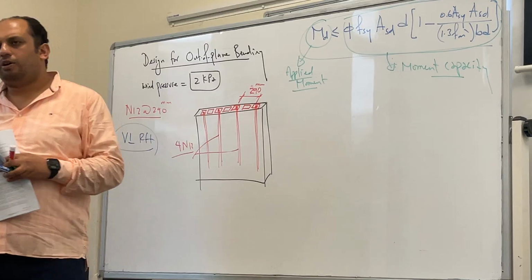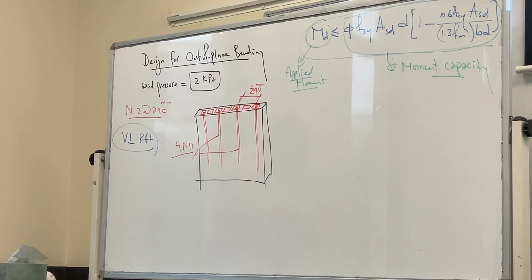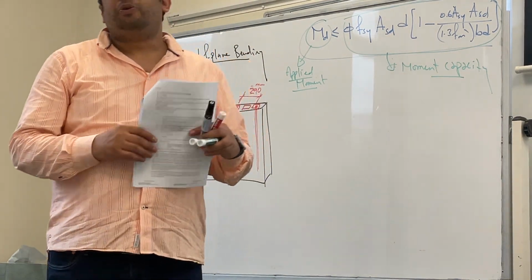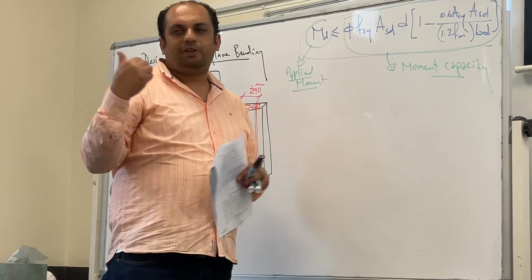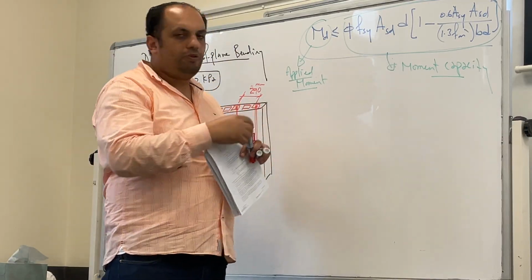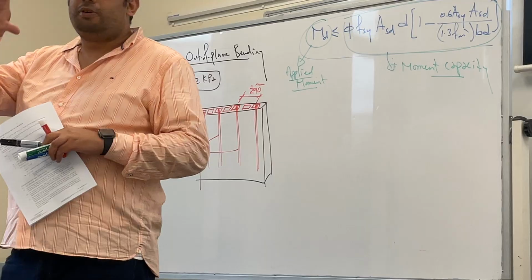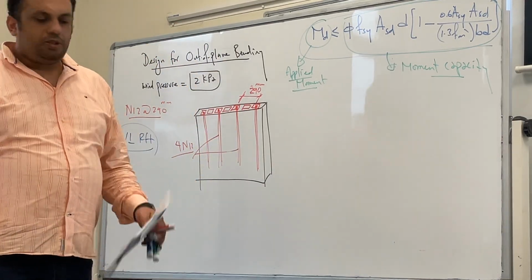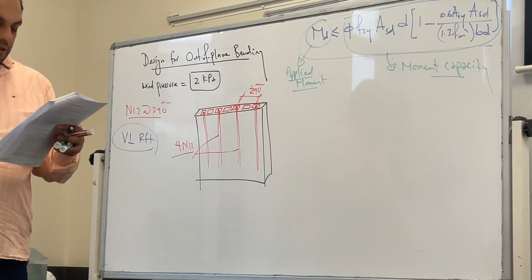How can we calculate the applied moment? Well, we can multiply the pressure by 1 meter. Which one is the more critical mode of the three? The top one, because of the connection to the roof. The restraint of the roof is the weakest one, if you remember. But anyway, 0.85. If you don't know, you can check. But we have tried this before, and we found that the connection at the roof will make the buckling or the slenderness of the top wall the critical one. Okay? So how can we start? Any advice or any suggestion?